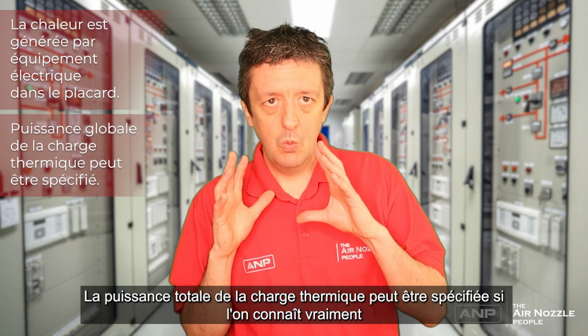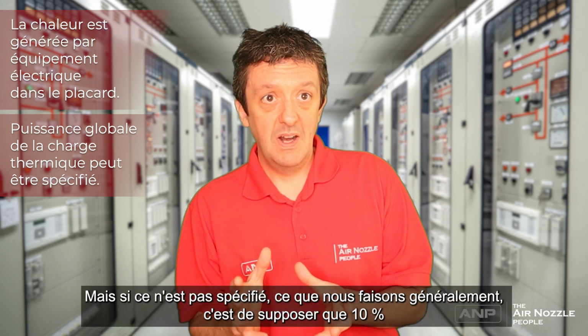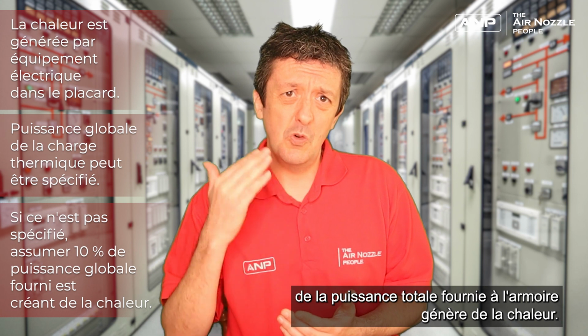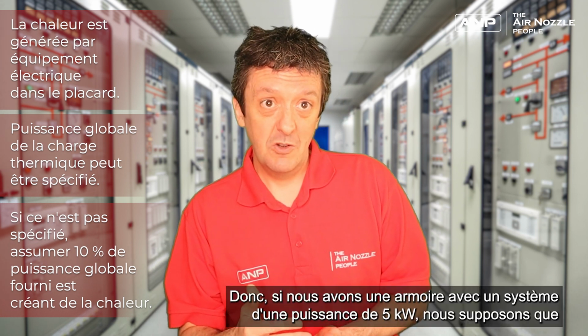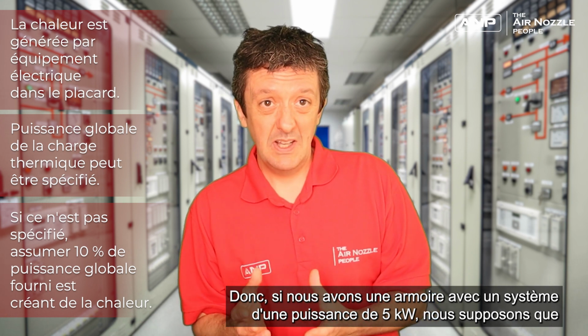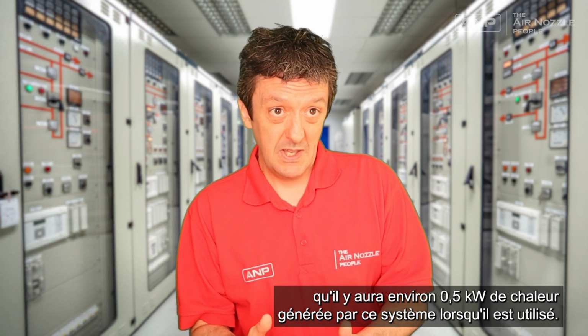The overall wattage of the heat load may be specified, if we really know the equipment in there, but if it's not specified, what we typically do is assume 10% of the overall power provided to the cabinet will be generating heat. So if we've got a cabinet with 5 kilowatts of kit in there, we're assuming about 0.5 kilowatts of heat will be generated by that kit when it's being used.